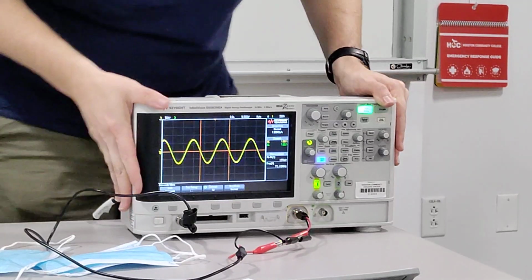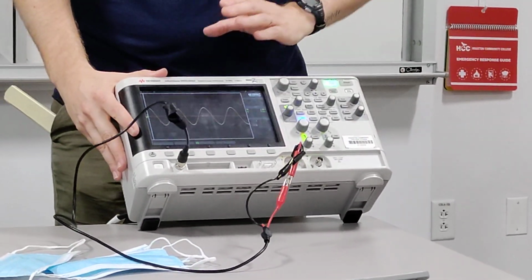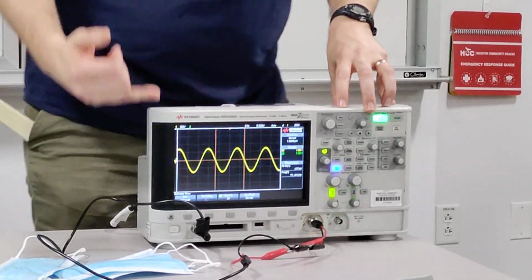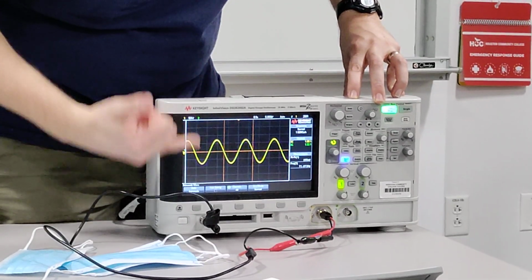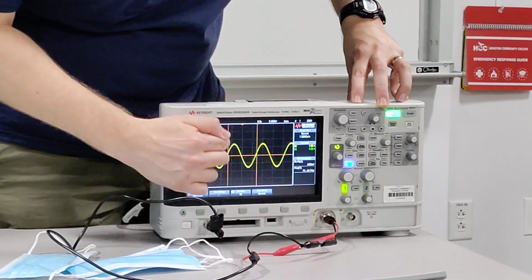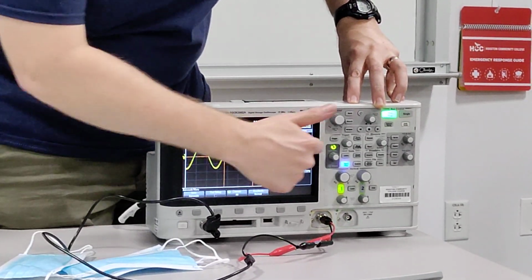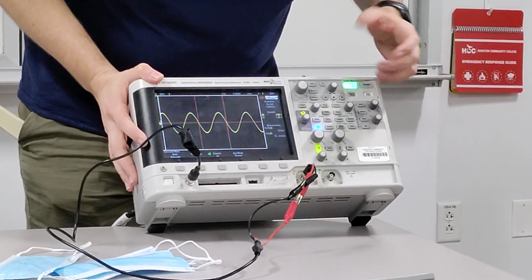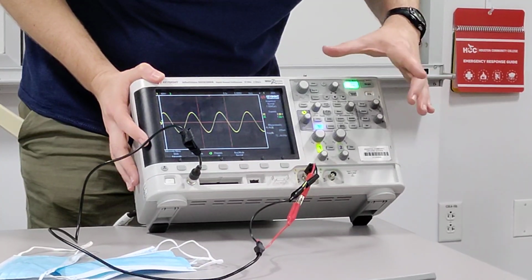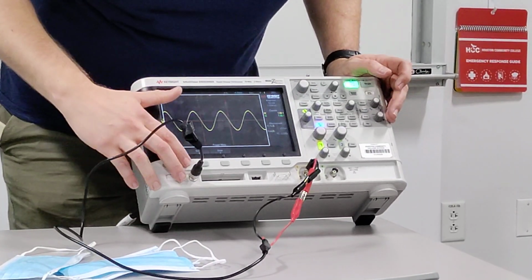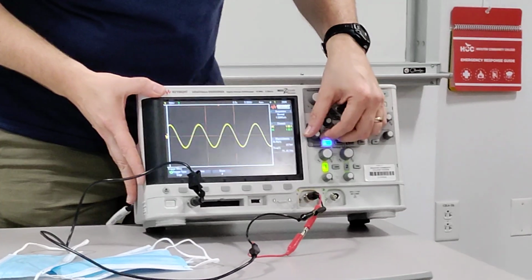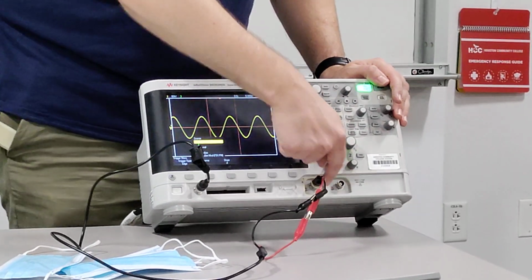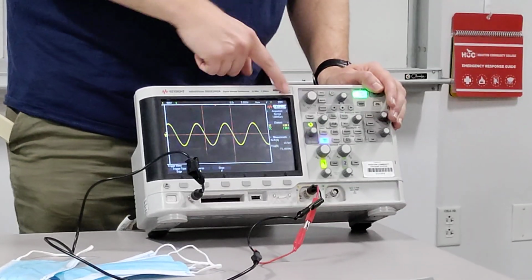Okay, what else? The oscilloscope knows when to take a picture because it's got a trigger point. It's got a rising or falling edge signal trigger. So as the input signal rises above this trigger line here in the middle, that's determining when it's trying to take an image of the signal. So if I hit trigger, which is there, I can change the trigger type from falling edge to rising edge if I want to. I can change which channel input it's deciding to actually take that trigger from.